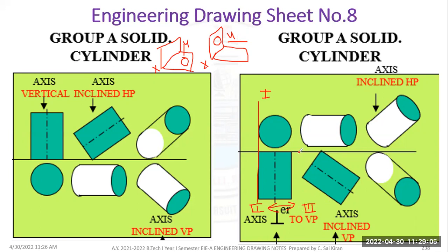So the same object I'm rotating at an angle of phi, and I have to make the projection. Stage 3 I need to project to get stage 4. Here stage 4 and stage 5 have the same dimensions or same characteristics of the object. I'm just rotating the axis. This is my axis. This axis I'm rotating at an angle of theta, and this will be stage 5. Then for this stage 5 I have to make the projections, and I'll get this as my stage 6.